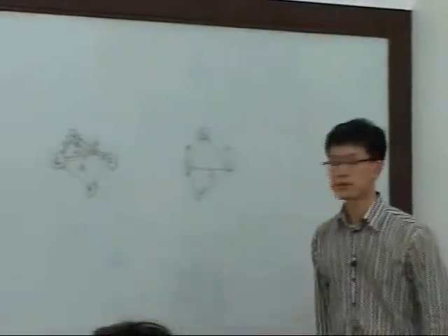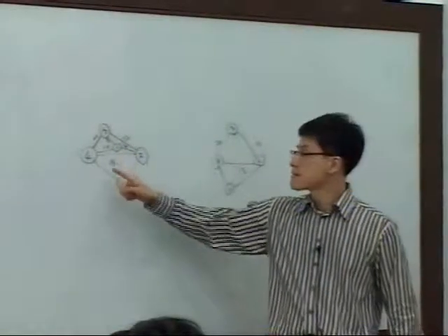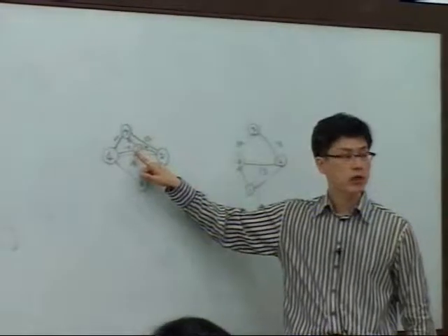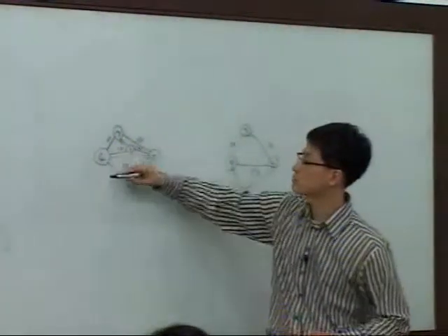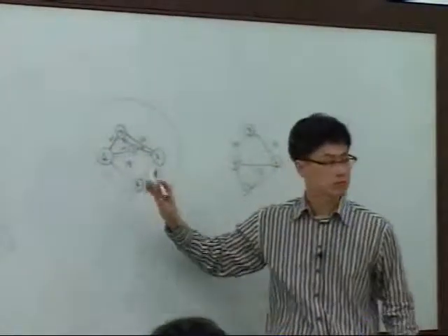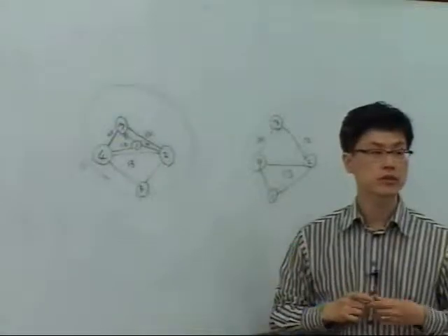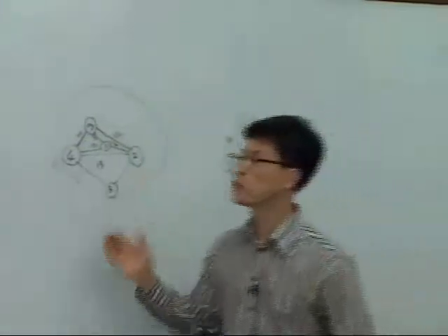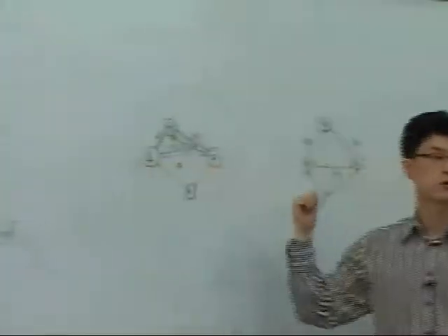However, you always have to think about this one. You know, there are many practical things like this. If this distance is like this, but the space requirement of number 1 is much larger than that, you can end up with 1 being big enough like this and 4 around here, which is practically impossible. If that's the case, you have to go back to the relationship chart and do things again.